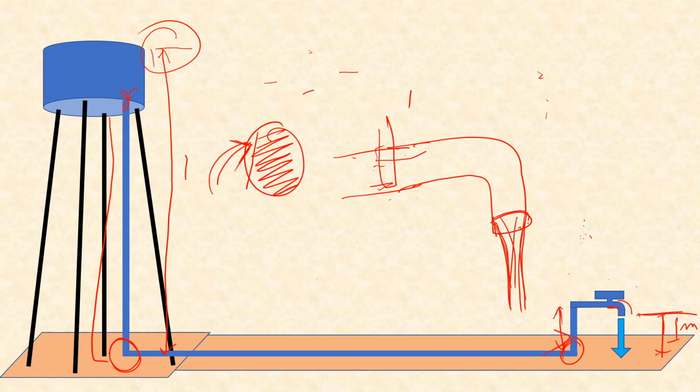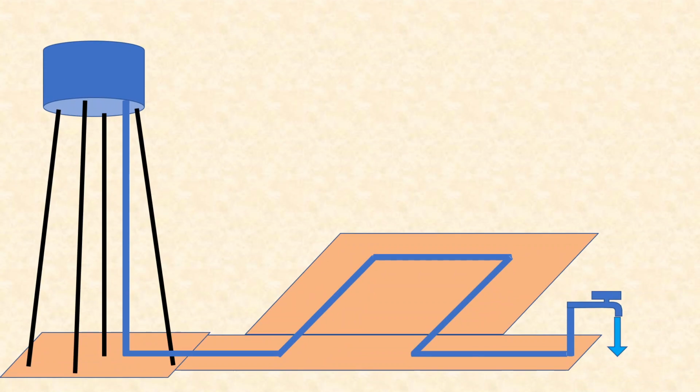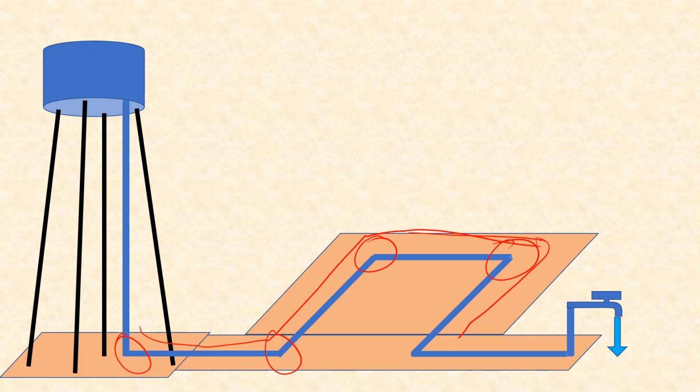Now let's take another example that you can practice on your own. So it's an example where we've used some unnecessary bends, so you can keep adding more and more bends and therefore more loss coefficients here, here, here, here, and so on, and then add the frictional losses for this pipe segment, and so on, and again here, here, here.